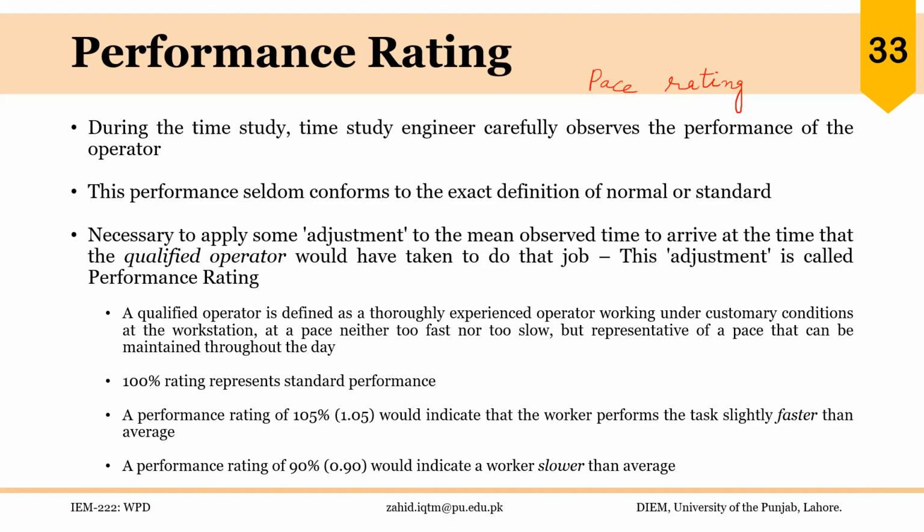During the time study, the engineer carefully observes the performance of the operator. This performance seldom conforms to the exact definition of normal or standard. So it is necessary to apply some adjustment to the mean observed time to arrive at the time that a qualified operator would have taken to do that job. This adjustment is called performance rating.